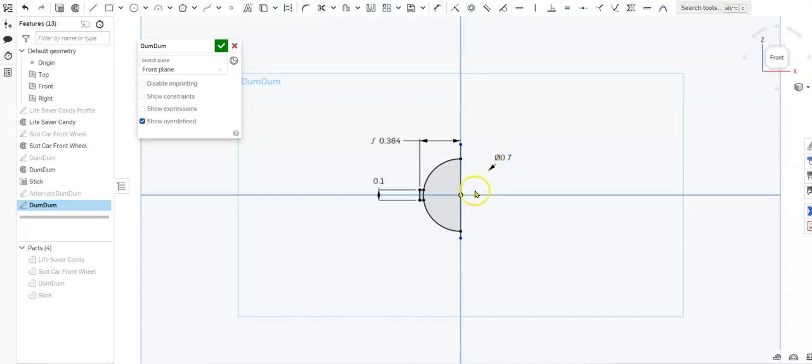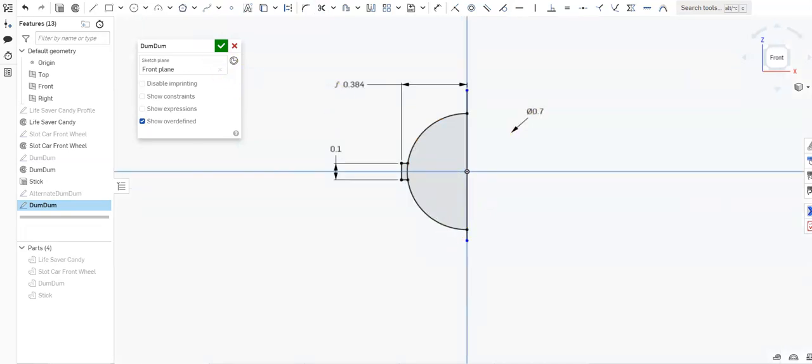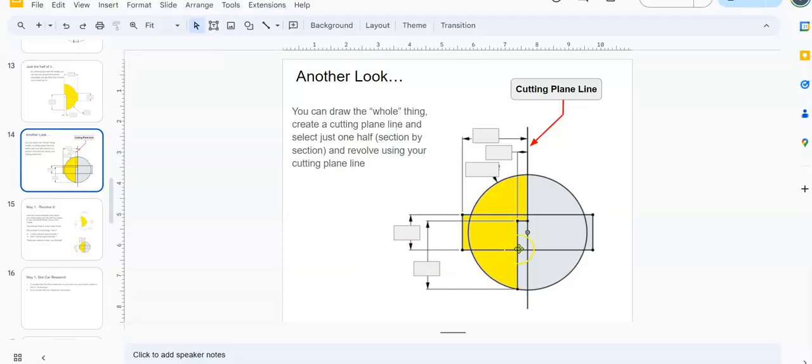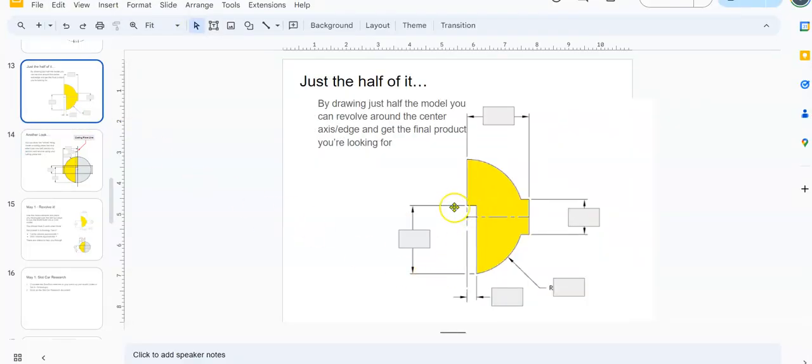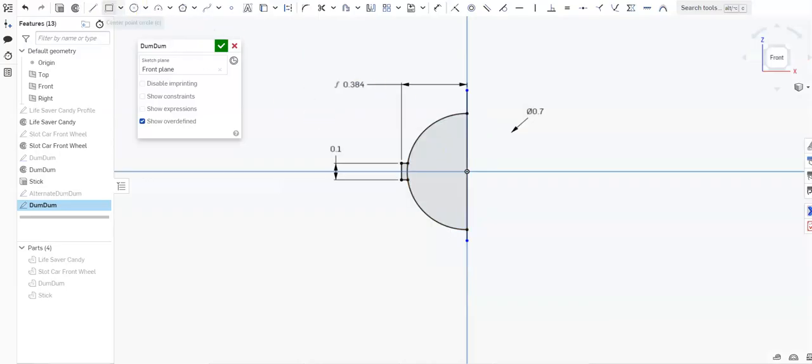I'm going to go ahead and trim away the extra material here. Don't need that. And then we're going to put in that section for the lollipop stick. Again, the section right here, you see a cutaway for the stick. That's just a horizontal line and a vertical line above the center. So line tool from the center line over, and then come straight down to the edge. Hit the escape key, trim away the extra parts I don't need. And now it's a matter of dimensioning those.